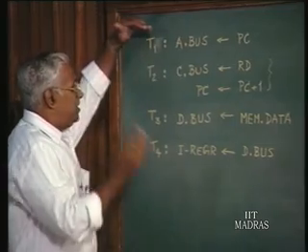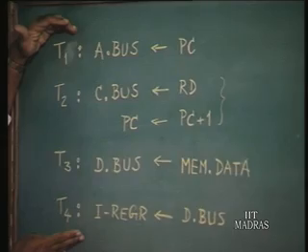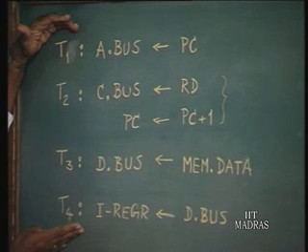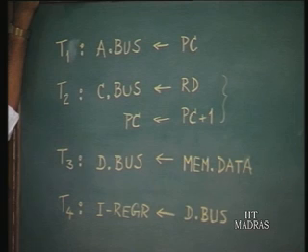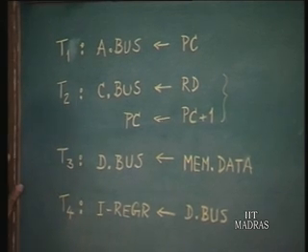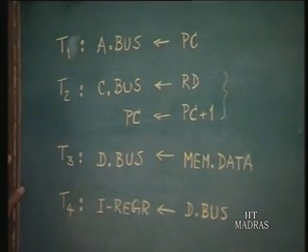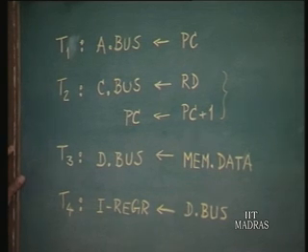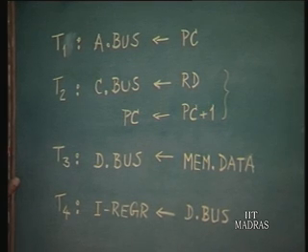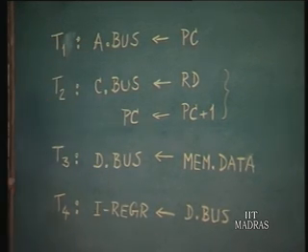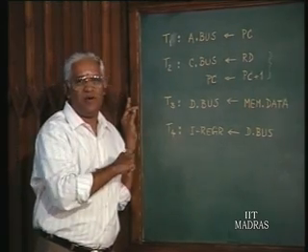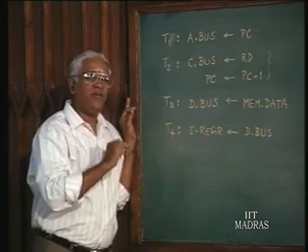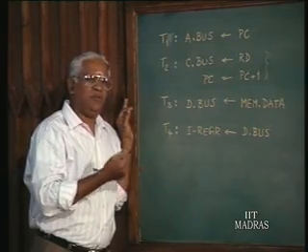Now, earlier we were talking about the states, specifically 4 states for instruction fetch, that is only one machine cycle, and we were working out the details. What exactly is the purpose of working out the details? Essentially to design the processor, because the processor consists of data path and data path control, and these state signals describe the data path control, which helps set the data path. And then for one specific architecture, we just took some typical architecture.